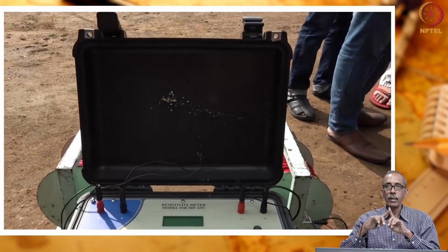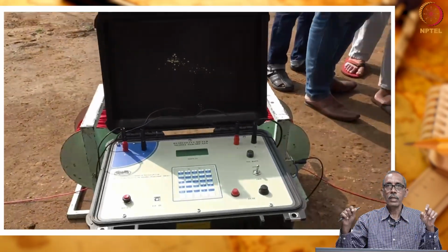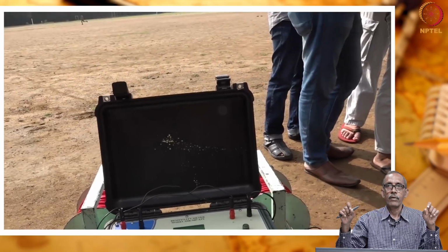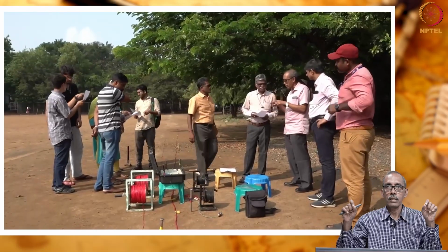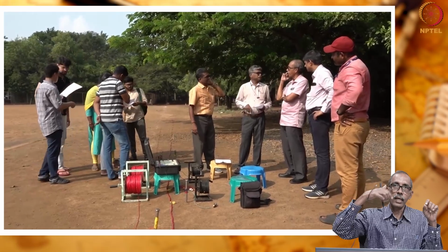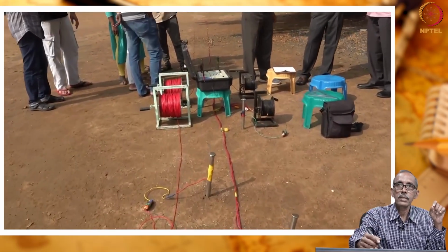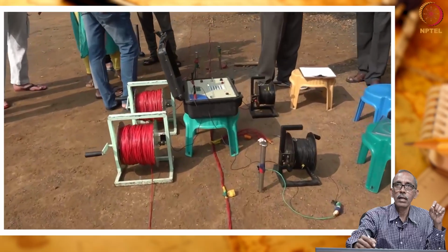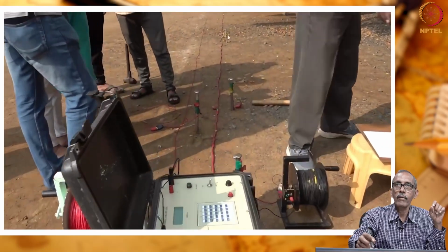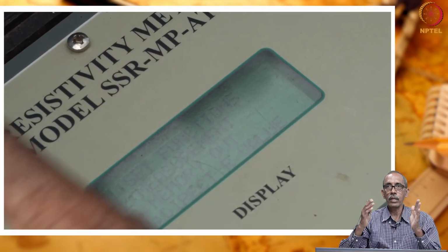At first, we are commencing our measurement by keeping the potential electrode at half a meter from the center. Then you can see the straight line, right. Along the straight line now we have, I hope you can see my cursor, this red line, is going to be our placement of electrodes. So, initially we have kept the potential electrode very close.